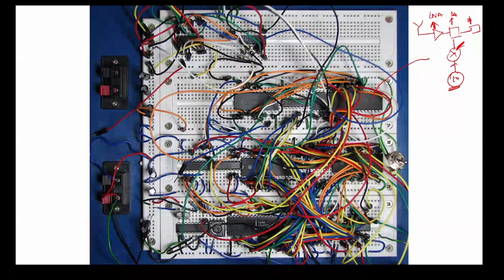If you want to make that receiver architecture on a breadboard, matching will be one problem, because if you are coming out of a chip, you need to match it at 50 ohm. 50 ohm is one standard. Then again, you are going back to a chip, so you have to ensure 50 ohm matching here. Similarly, with each IC in RF IC communication, you need to worry about the matching. If the dimension is larger, say you are designing something on PCB itself, you need to worry about matching. If you are coming out of the chip, you need to worry about matching.